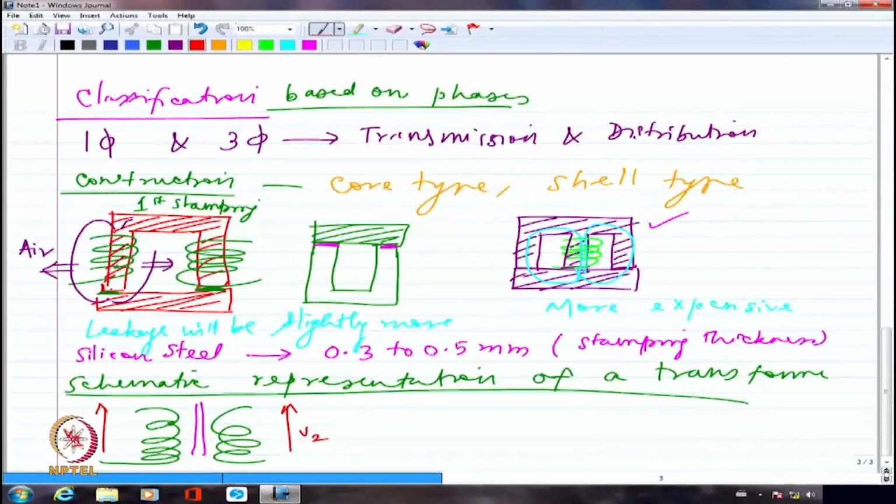The reluctance is really, really small, because the reluctance is small, to establish a nominal flux, I will require a very, very small amount of MMF. Ideally, I should say literally 0 MMF should do it. It's not true. Reluctance is not 0.